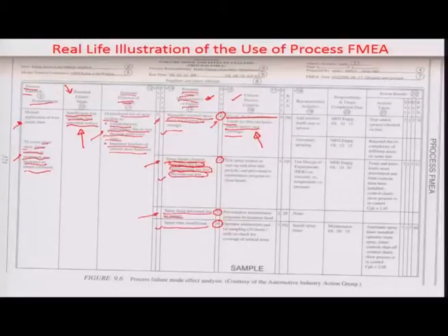Similarly, for the spray head clogged, there is a test spray pattern which is utilized at startup and after idle periods. There is always a possibility that the wax being dispensed out of a wax cylinder, which comes from a vendor, may have different parameters like viscosity, temperature or pressure dependence, and it may result in lower flows through the spray heads, and some remnant wax inside the spray heads may get clogged and make the orifice smaller.